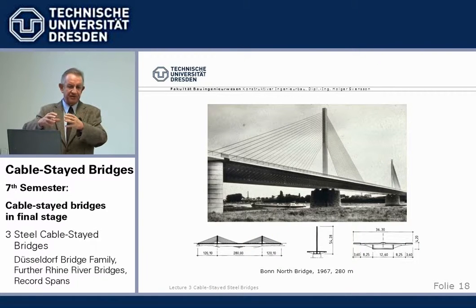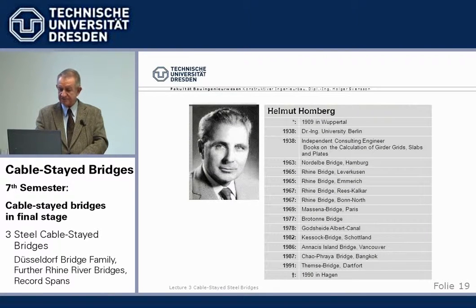And because the concentrated stay cables consisted of several ropes, they were difficult to protect against corrosion. You cannot get to the inside, you know. There were all sorts of tricks, but with time they all corroded. So those are the main advantages. Simple stays, simple anchorage, simple construction. Big step, and that is, with some exceptions, the type of stay cable bridges we use with multi-stays.